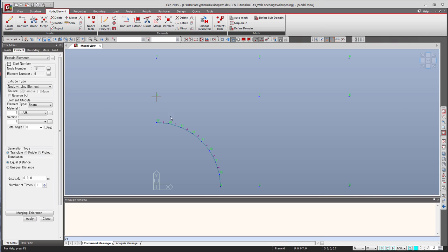Now I want to create 8 plate elements between this beam and those 3 nodes. So you see probably that I need more nodes between these 3 nodes, otherwise I cannot connect the first plate element here. So to create these elements, what I'll do is that I will divide these nodes and add here. So you can do that.